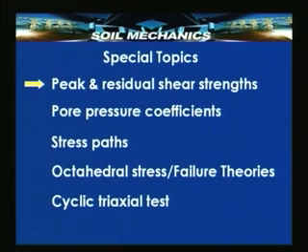Then, what are stress paths? I had mentioned that the shear strength of a clay soil particularly depends upon the stress history, so one needs to know the path through which the stresses have changed. Then we need to know something about failure theories.